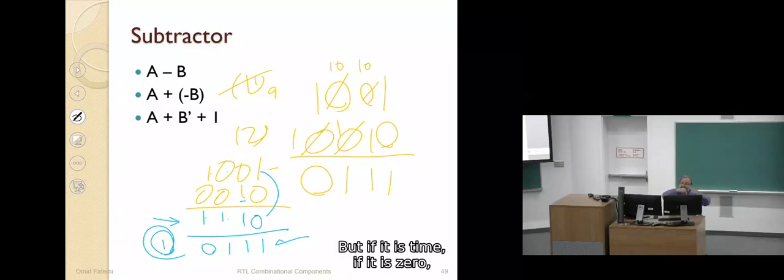But if it is 0, it means that we had a borrow for our subtraction. In addition, when there is a carry, it means it is not complete in, for example, 4 bits. We needed another bit. If there is 1 in subtraction, then it means that everything was okay. But if it is 0, then it was not okay. We needed another bit.